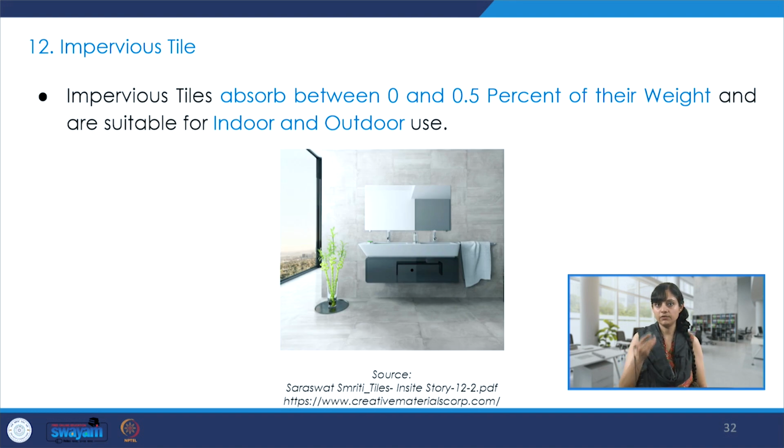There are also impervious tiles. They absorb between 0 and 0.5% of their weight, and they are suitable for both indoor and outdoor use, again depending on where they are getting applied and what the percentage of absorption by weight is.